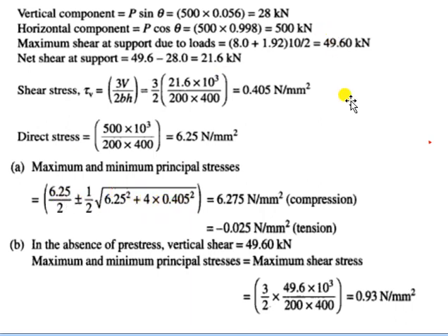At the support, f of x is equal to P by A. Nothing is given about vertical pre-stressing, so f of y will be equal to 0.